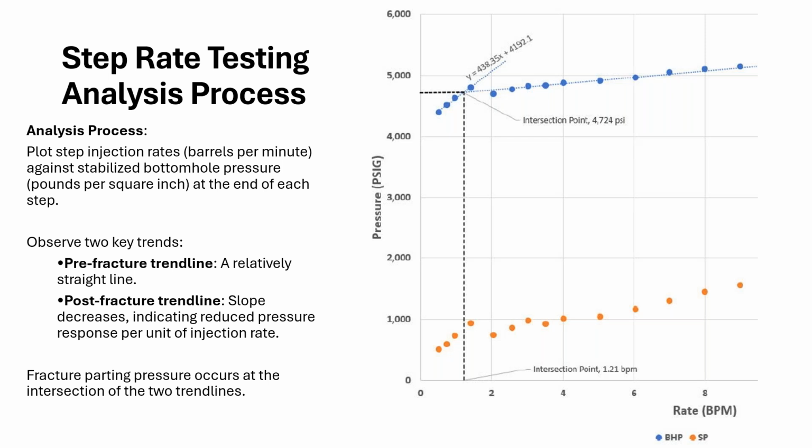What are some of the issues with each step not lasting the same length of time? Well, if you have a step that is shorter in duration, your pressure may not be allowed to build up long enough. And if you have a step longer in duration, you may overpressure that step and it could get off trend because your prior steps are at 30 minutes. If you did a step that was 25 minutes, it may not have built up 5 minutes of pressure during that time. Or if you had a step that was 35 minutes, it may build up excess pressure during that time.